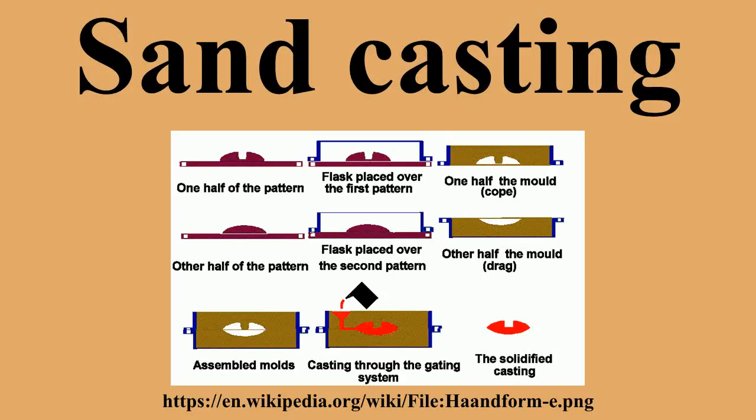In the late 60s, mold compaction by fast air pressure or gas pressure drop over the pre-compacted sand mold was developed. The general working principle for most of the horizontal flask line systems is shown on the sketch below. Today there are many manufacturers of the automatic horizontal flask molding lines. The major disadvantages of these systems are high spare parts consumption due to the multitude of movable parts, the need for storing, transporting and maintaining the flasks, and productivity limited to approximately 90 to 120 molds per hour. Vertical sand flaskless molding.